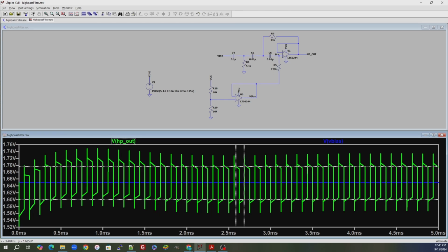I want to reduce my work on the microcontroller, and I just want to read one voltage. I just want to be able to read the peak voltage and know that it is what it is. And of course, we could say, well, I know that my center point is 1.65 volts, so I can just double it. I can just read the maximum value minus the 1.65 volts of the bias and call it a day. But we don't want to do that, right? We want to be able to see this entire swing and be able to monitor and do a reading on this actual signal, not have to deal with math on our bias point. And the reason why is because if there's some discrepancies in this bias point, we won't see it on the output, right?